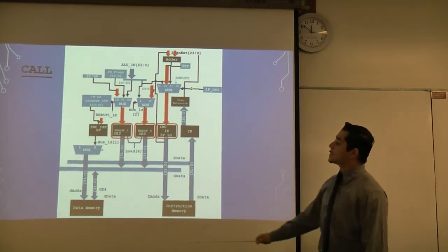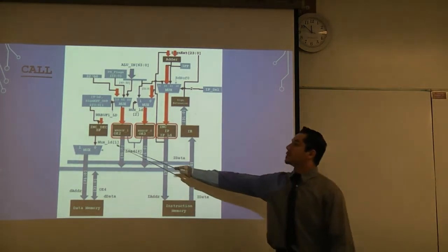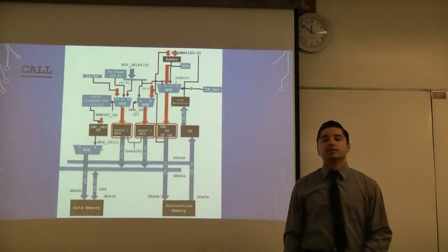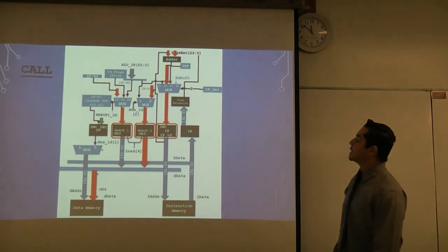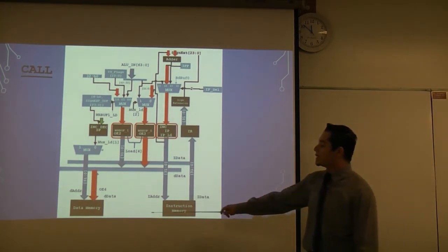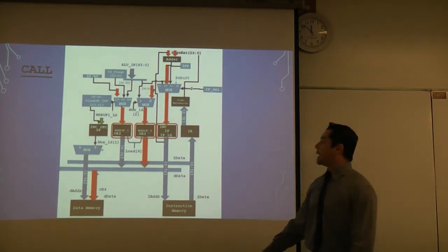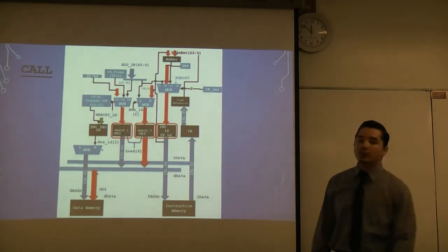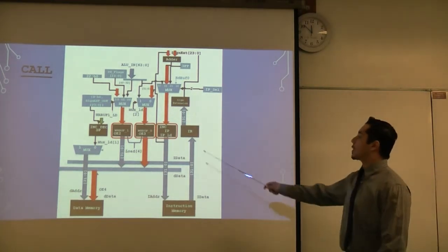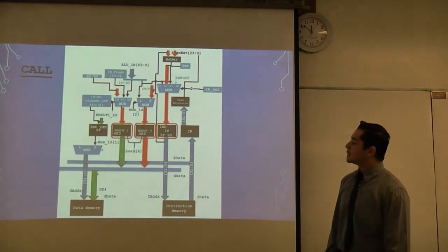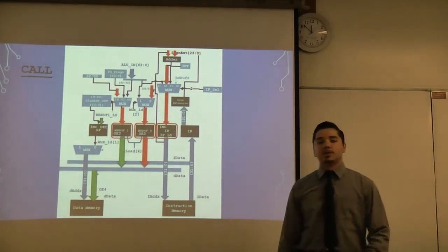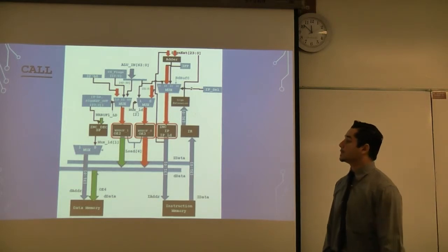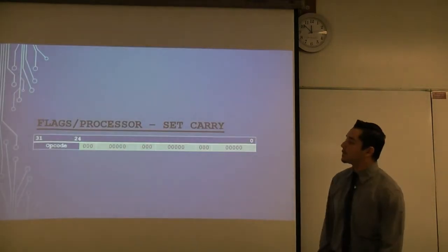And you have to make sure that your stack pointer is going to be decremented for the next time that you go around to go on to the next part. On the second state, that's when you're actually going into the data memory and going to the specific location of where you're storing the lower part to. On the third part, that's when you're going to be loading the upper bit, which is the 32 bits of zeros. So you're just pushing the zeros?